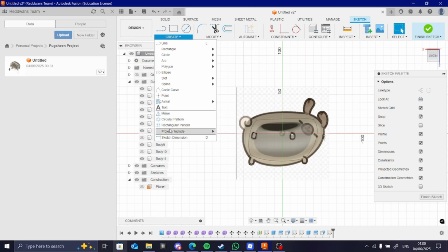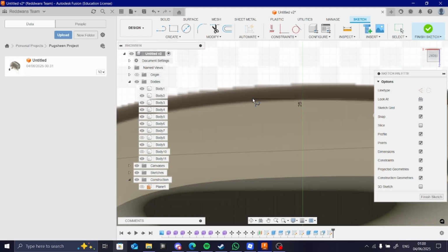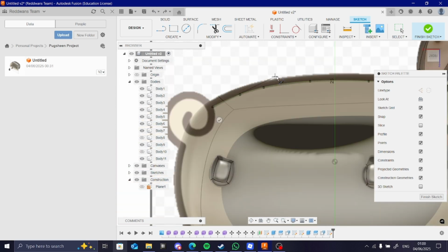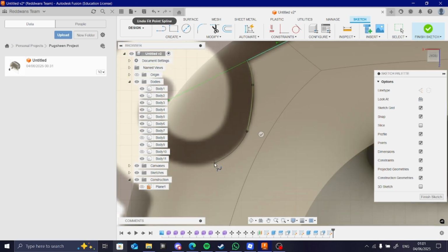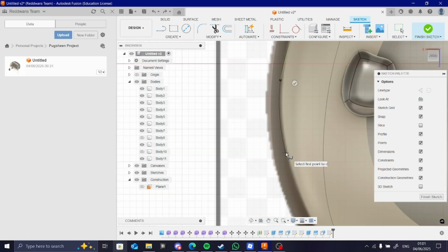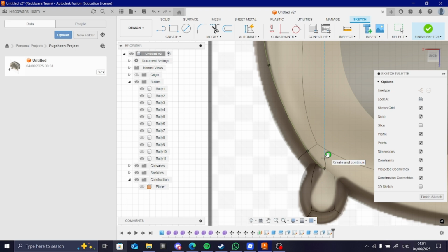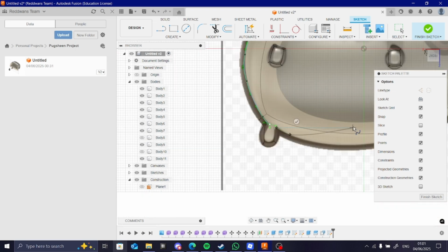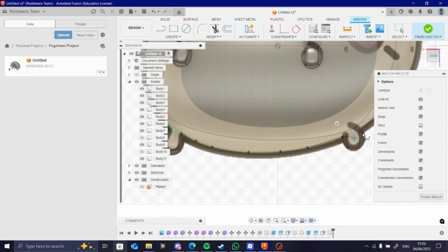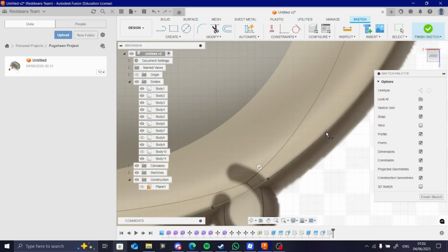The new part was adding the outline. Now for the outline of Pugsheen, I made a new offset plane, and from there I built, I guess you could say, a ring around that basically matched the whole body. I hid some parts, like the tail and the ears, so they don't get in the way. And I essentially traced that all around using the fit point spline tool.